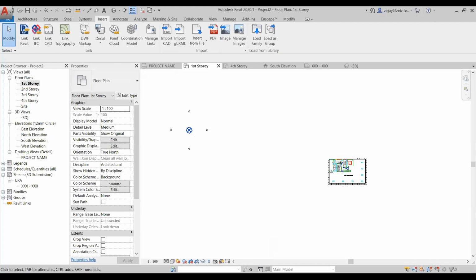So eventually, when you're linking CAD files for several floors, it's a good practice to be aware of the origin point of all those floor plans. Ideally, it should be in the same place for all the plans. For example, if you have grids, it's best to put that origin point in the intersection of grid A and grid 1 so that it's consistent across all the floors.